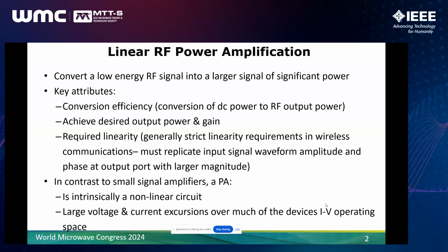And then with respect to linearity, all of our wireless systems, whether it's mobile or infrastructure, have fairly strict requirements in terms of the linearity. And we can think of that in various ways, but in the end, we need to replicate the input signal waveform, both the amplitude and phase of that waveform, at the output port with much larger signal magnitude. So if you're a little bit new to PAs, this is different in several ways.